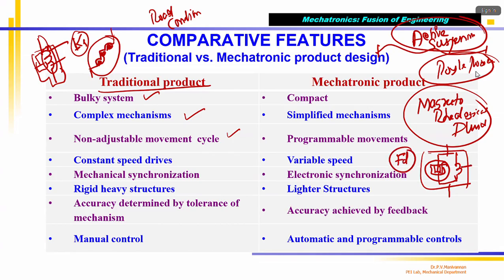Similarly, the spring has a stiffness. When a force is applied, it gets compressed, and this opposition force we call spring force. The damping force and the spring force are responsible for absorbing the ground reaction force when the vehicle is moving over an uneven surface, when the road is not flat, correct? That absorbs so that the passenger is not affected by the ground reaction force, what we call FG. That generates a vertical acceleration, which makes your vehicle move up. Anyway, don't worry, we will talk about that. I will explain the spring mass damper system.